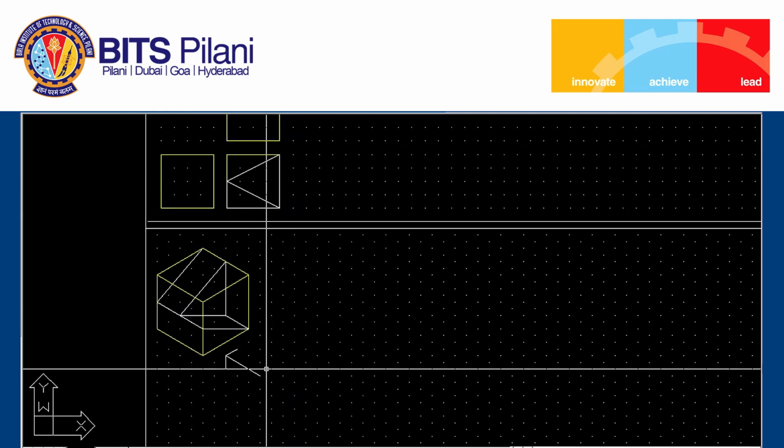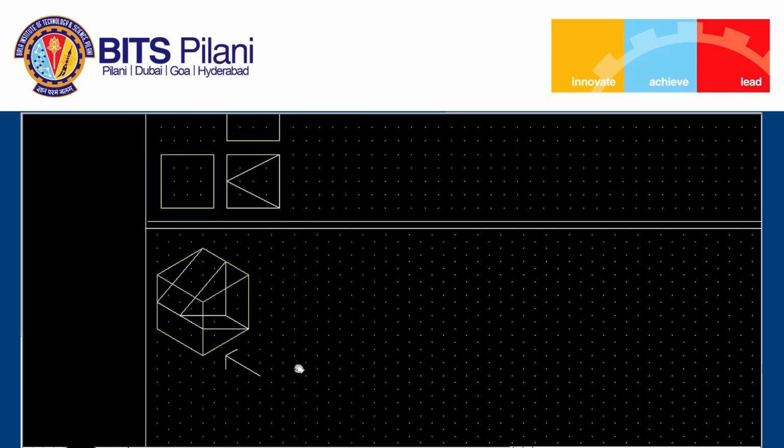Now we have drawn both the principal surfaces. Now we will see the other surfaces. This is a principal surface which will fall into a line view, which is automatically satisfied here. The inclined surface will fall into a line view in the front view, so it is also satisfied. This inclined surface also falls into a line view, that is also satisfied. So all surfaces are satisfied here.